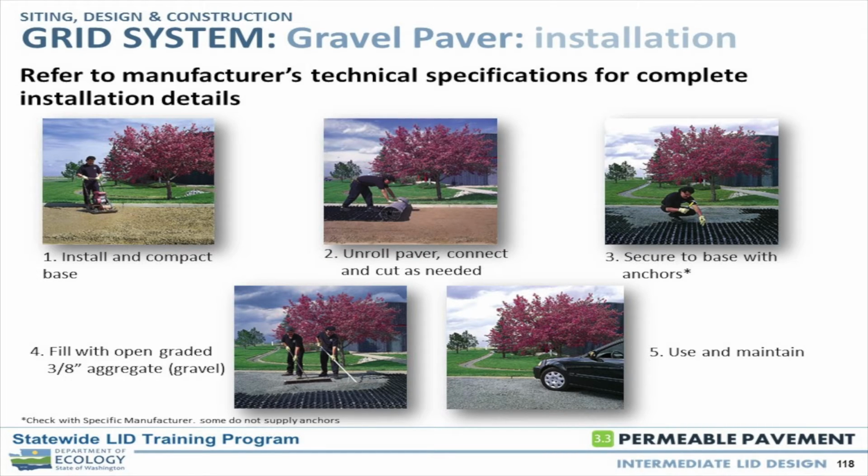You want to maintain that aggregate just above the rim of the plastic grid. That can be challenging. Otherwise, it's exposed to a lot more wear and tear. But that's the recommendation, and would be one of your maintenance considerations.